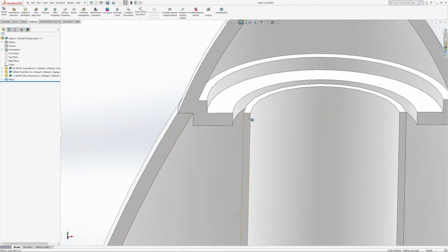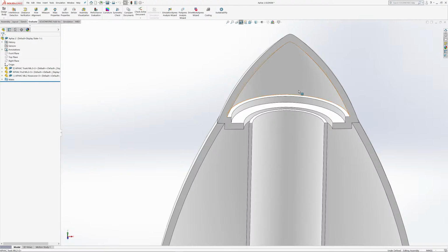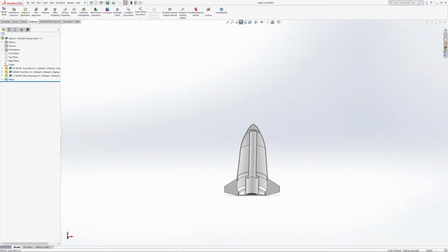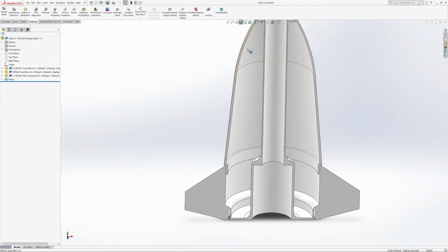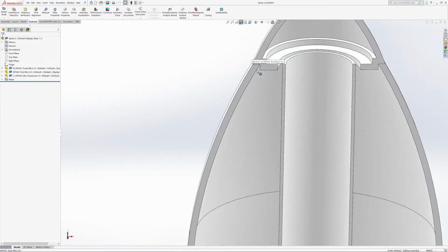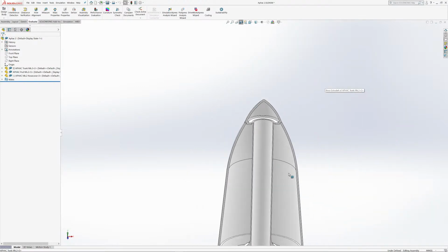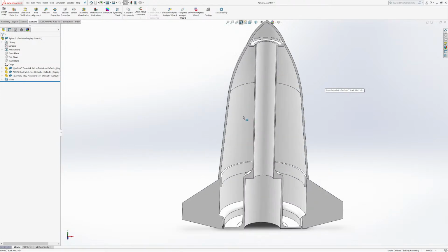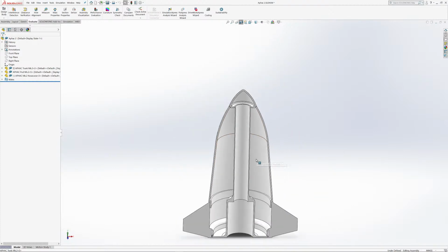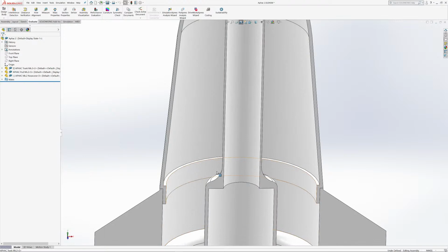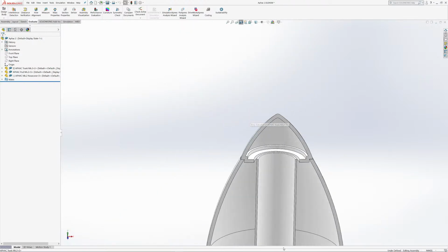this whole section. There's a gap here, and that's because this nose cone was based off of the old design for this, which just had a static tube going all the way up to the top here, which isn't what we want anymore. Now we're going to want to redesign both the base here and the nose cone. The aeroshell is going to remain mostly unchanged, but up here we're going to add a bit of an overhang with a fillet. Fillets are very helpful because they help you to print bigger and bigger overhangs without support material.